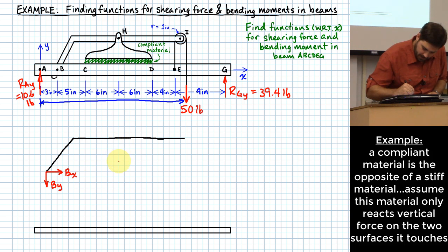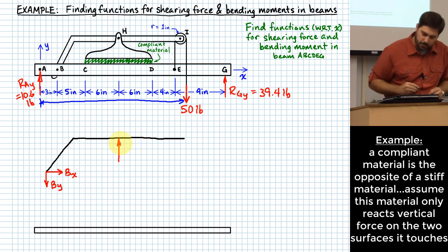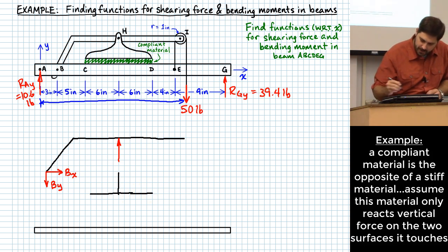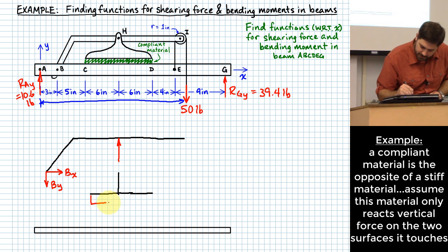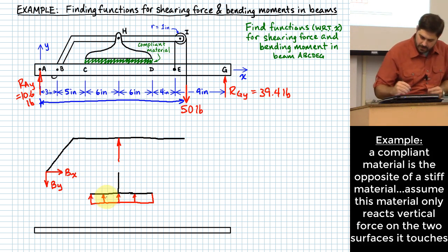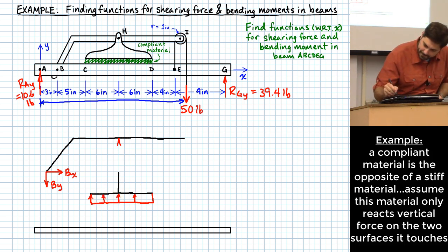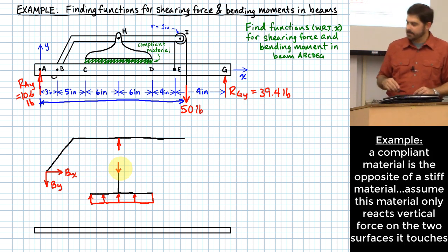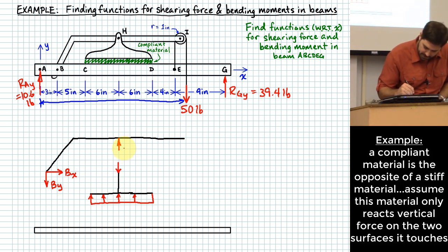I would say it looks like a force would act upward like this. The reason I know that is I can do another, maybe simplified, version of the little shoe thing that's pressing on the meat. The way I would model that is with a distributed load along the bottom side of the shoe, with a force acting downward like this. Let me call this maybe just RH.